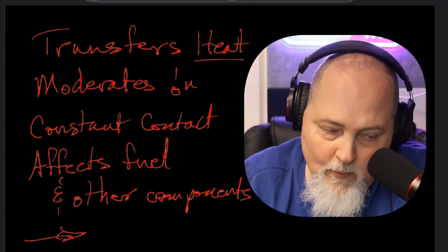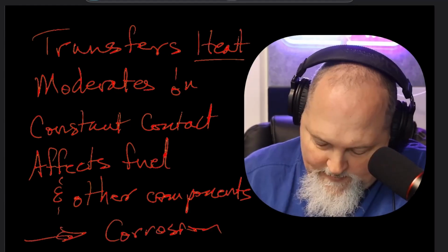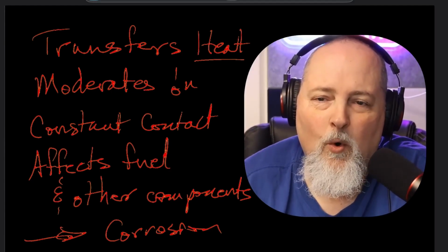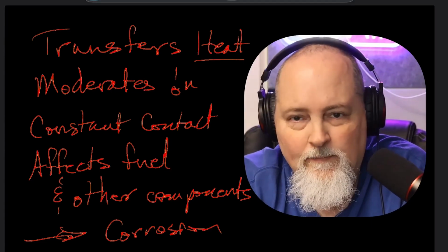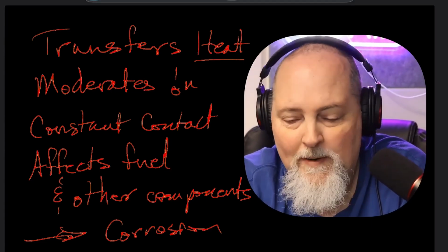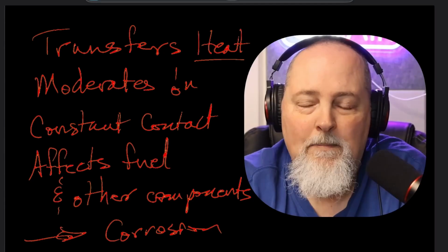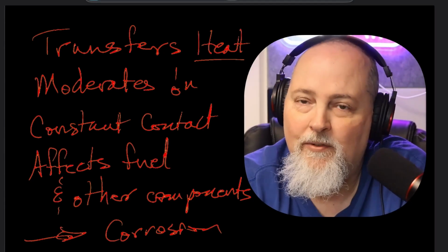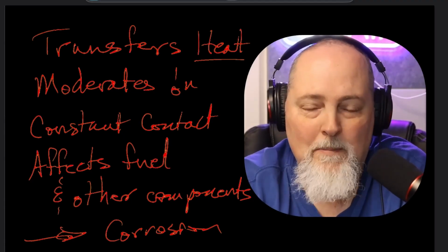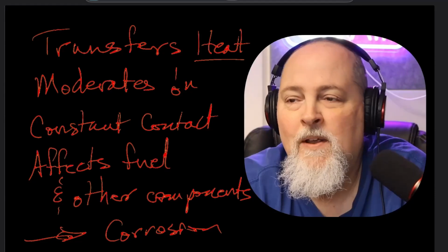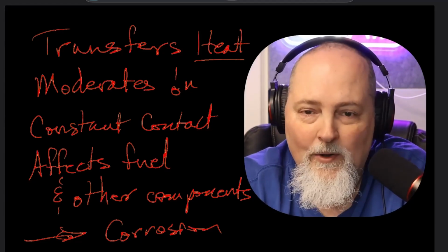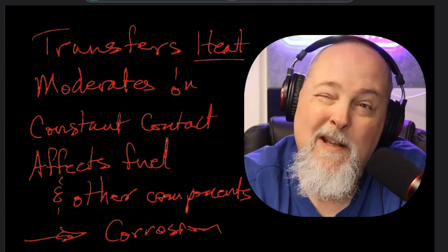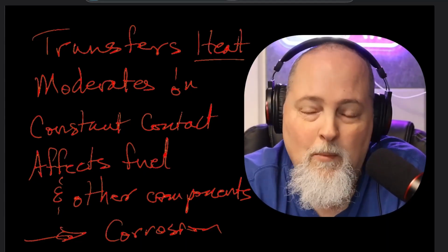Why? Well, one of our biggest concerns is corrosion. So overall, all these things affect safety. So our goal is keep the water clean. We have all these demineralizers and filters, keep the pH under control, keep the chemistry under control. We add things we'll talk about like hydrogen in a boiling water reactor, and noble metals, and in a pressurized water reactor, we add things like lithium hydroxide, ammonium, boron, boric acid.